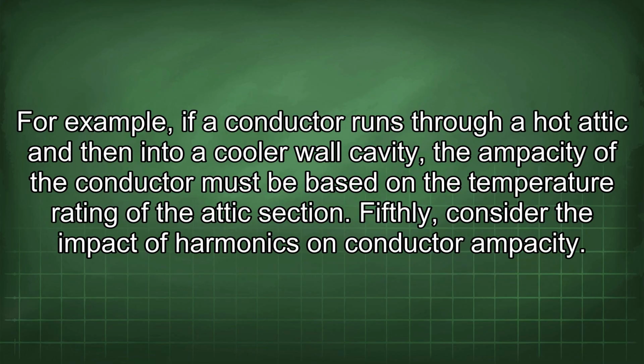For example, if a conductor runs through a hot attic and then into a cooler wall cavity, the ampacity of the conductor must be based on the temperature rating of the attic section.